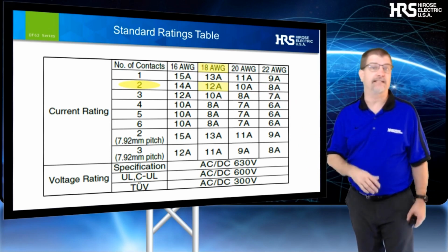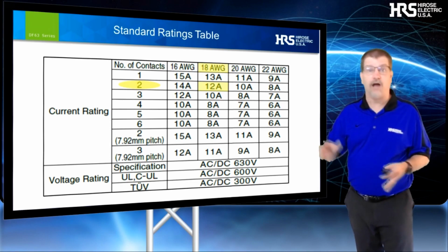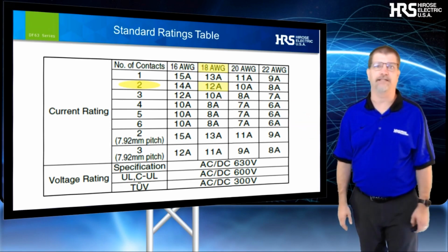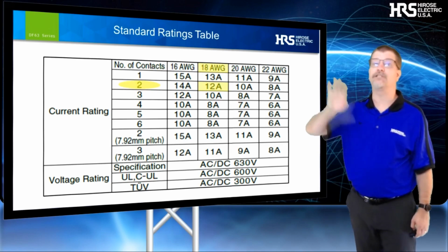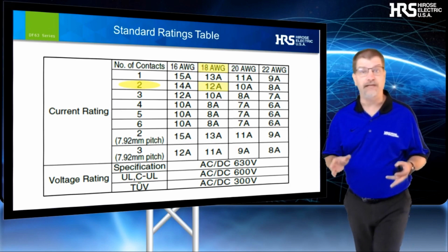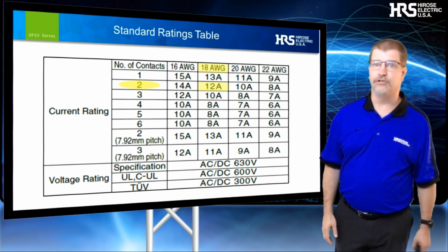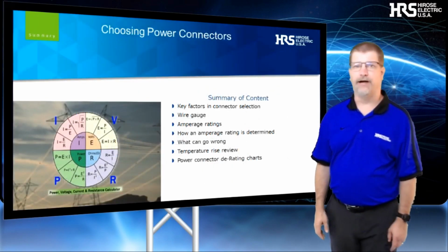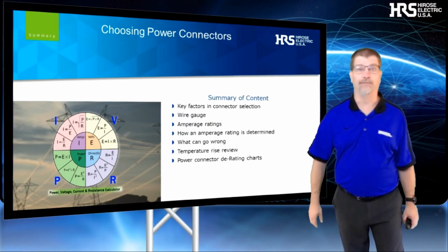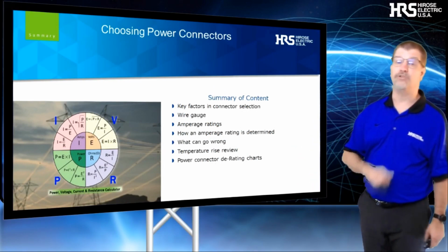If you're in a situation where you're splitting a single higher current, maybe in a smaller connector over multiple contacts, that's when we need to consider additional derating beyond what you see in this chart. And that value could be up to 1/3 the original contact rating. Wow, we've spent a ton of time on the amperage rating, and rightfully so. It is probably the area I get the most questions on.